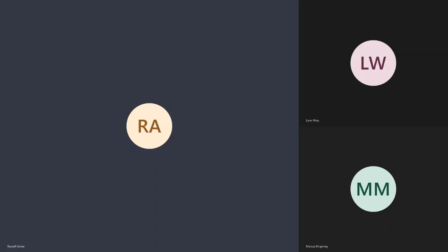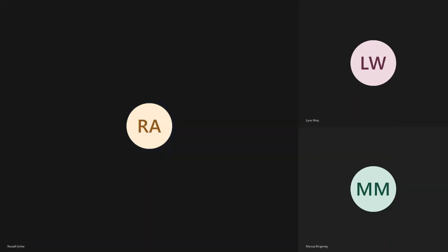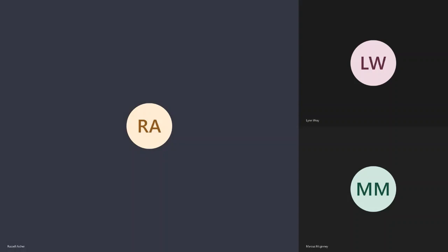Another method is running a dissolve, saying remove the boundaries on all polygons that have this value in the attribute table that touch. And then going in and editing: doing a sort on area, then deleting everything that has like 0.01 square meters because you know they're not really going to be useful.